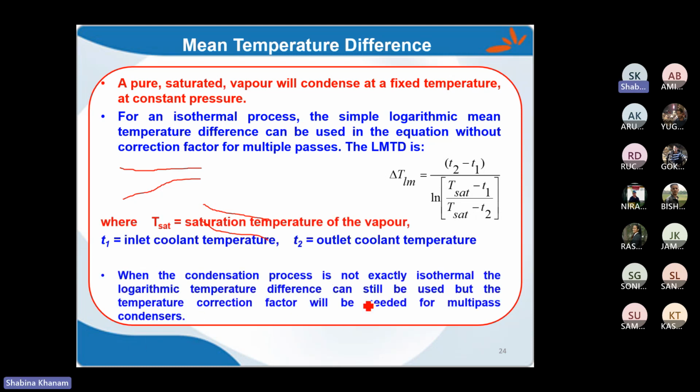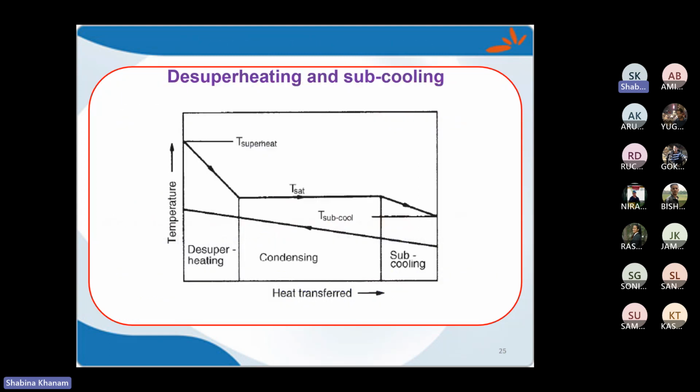Okay, this is the same thing. So if you are dealing with a mixture of components in vapor, then you should calculate the LMTD with the FT correction factor. In this way you can consider the mean temperature difference. Now, when I am considering condensation, so far we have discussed only this part. Condensation is occurring at a particular temperature, and second I'm having the coolant.